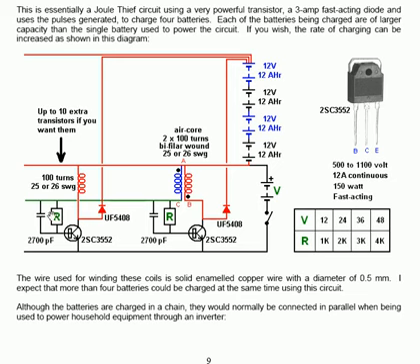The second one also feeds its plus through a separate wire to the plus of the batteries, and each of the additional stages has a separate wire going to the plus of the batteries. You may say, oh well, you could just connect the wires together. Well, yes you could, but it won't work as well. Those separate wires are important for a multiple charging stage like this.